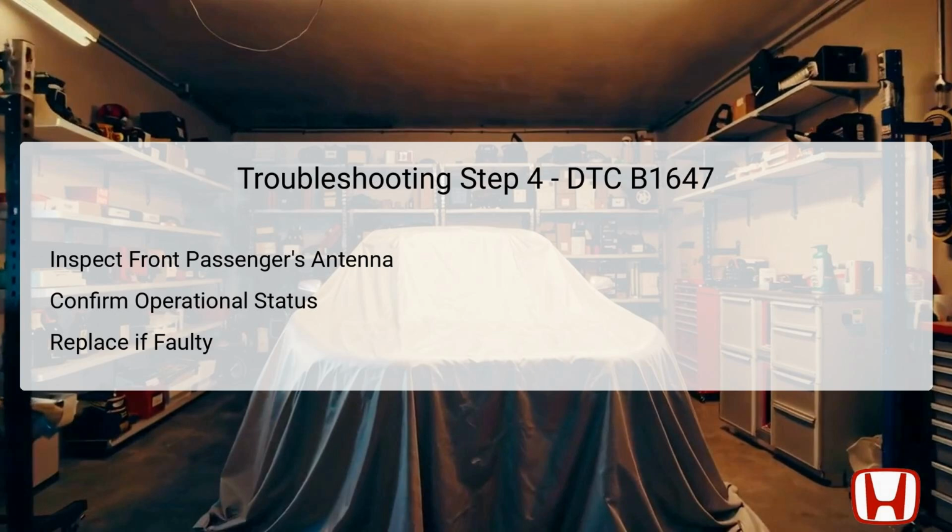Depending on the diagnosis, if the body control module and wiring tests are both clear, it may be necessary to replace the antenna component. This inspection typically involves checking for any physical damage or malfunction that could hinder its performance in signal transmission or reception. If the antenna is indeed found faulty, replacing it will remedy the circuit short and restore full functionality to the keyless access features of the vehicle.